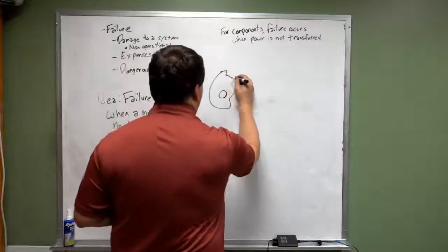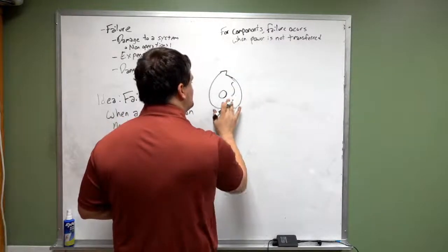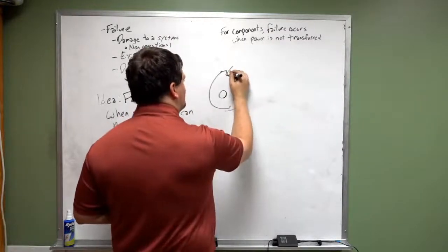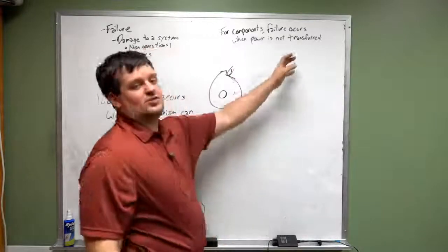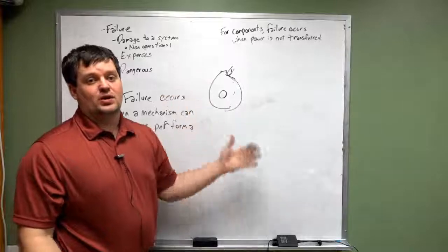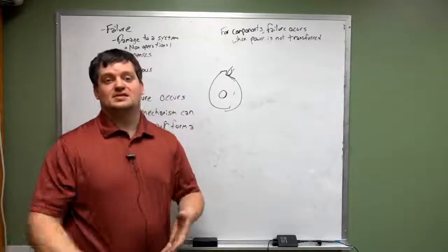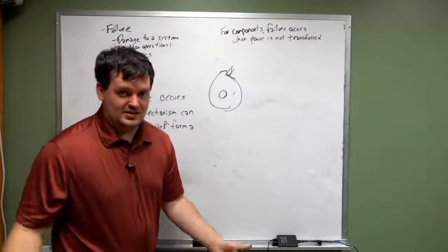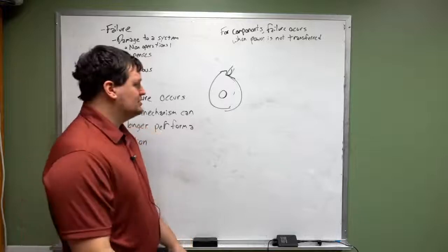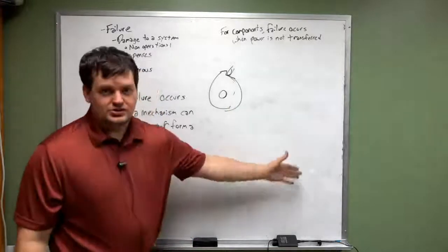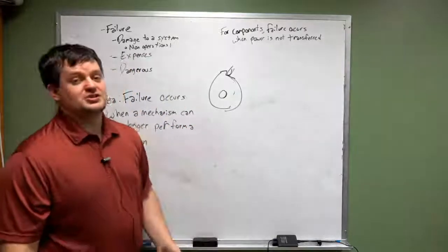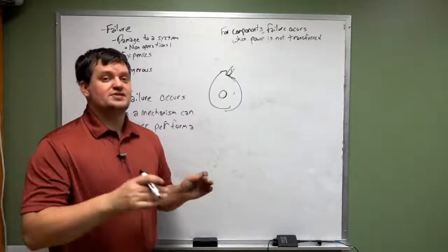If we have the full gear mechanism and nothing is wrong here, but we have components come down into the teeth and jam it up, then we have a failure where power cannot be transmitted out because the joint itself, again, is damaged. So, those three locations, input joint, linkage, output joint, are potential failure mechanisms for every single linkage.